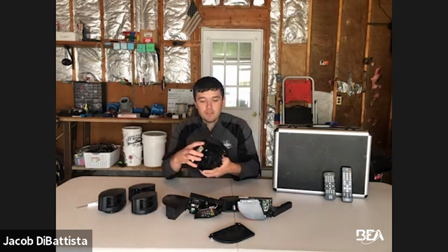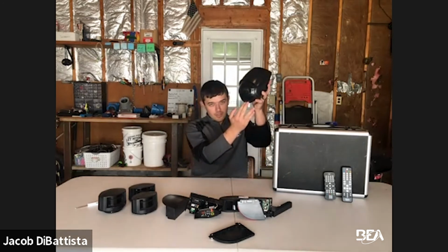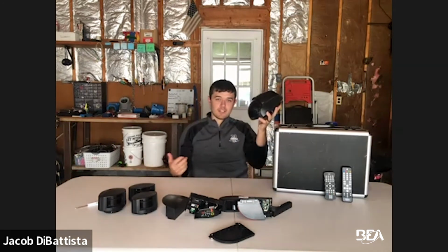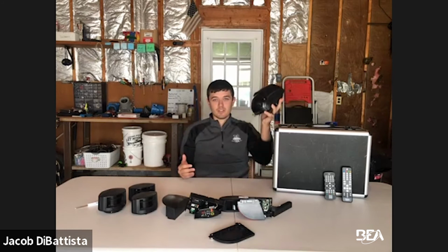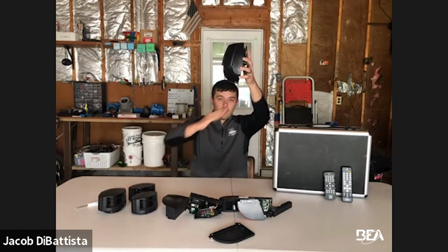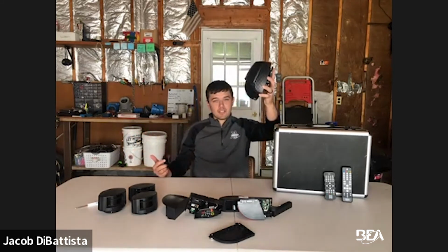The wide scan, if you can imagine this, it beams out the lasers down here onto the ground and it scans. There's a spinning mirror inside and it projects out 7 curtains. It's almost like a pyramid. There's 1 straight down, 2, 3, 4, all the way out. And whenever it sees something, this is the one that detects the XYZ coordinate, the XYZ measurements.